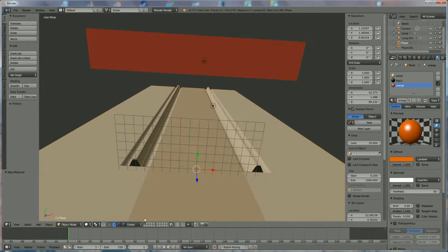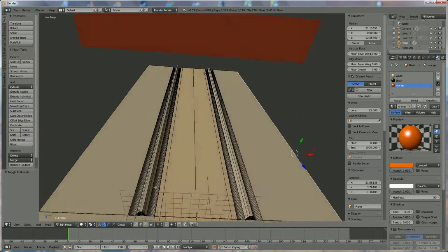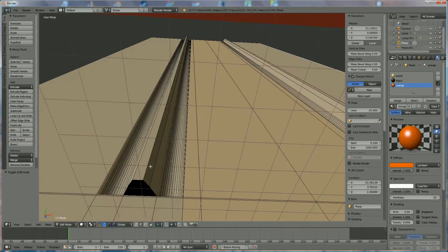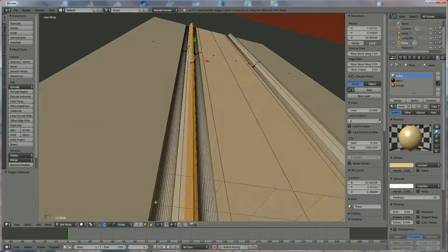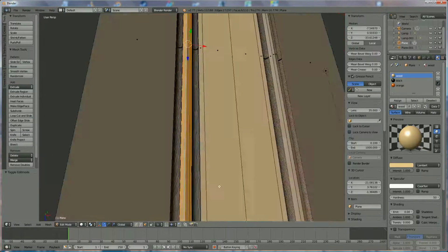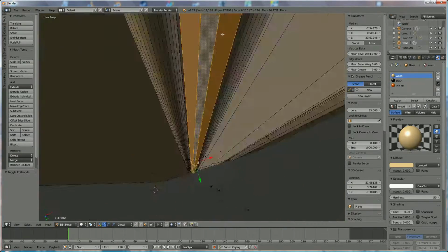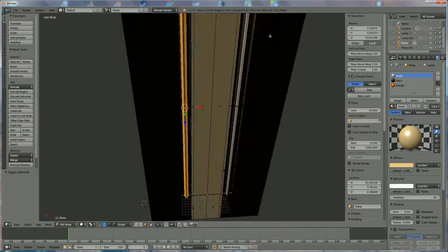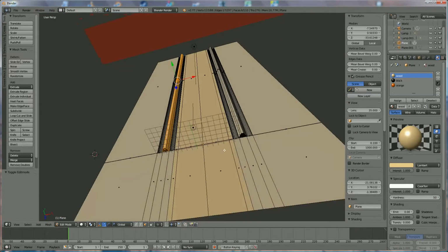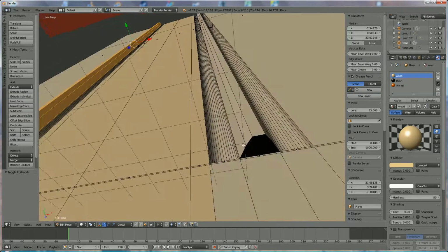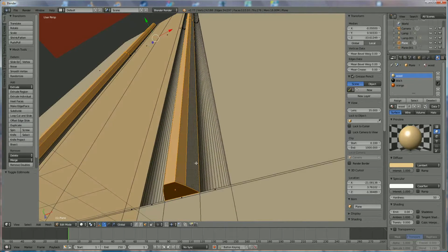Okay, to do now, we're going to edit mode and we're going to select a few points. First of all, to do that, we're going to select face selection. Just right click on that one, hold down the shift button. And we're going to select every face that we want to give it a color. Sorry, I left that open. You can close that of course if you want. It's not that important. Hold down the shift button, click on every one of that. And say orange and assign.